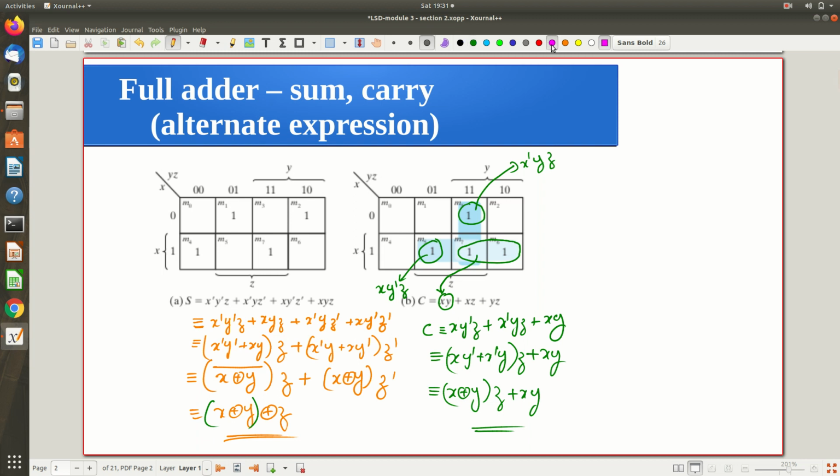So now what I'm going to do is, I'm trying to implement the full adder using half adders. So what I will do is, first I will take a single half adder. Let's see. So this is the first half adder I am having, half adder 1. And for this half adder I am applying the first two bits, that is xy, and Z is a carry, right? So the actual inputs X and Y I'm applying.